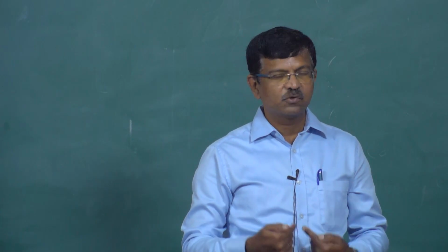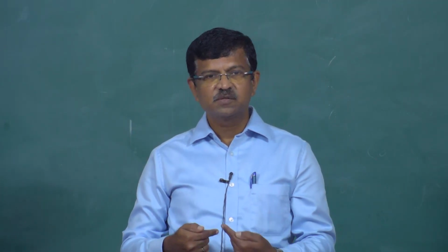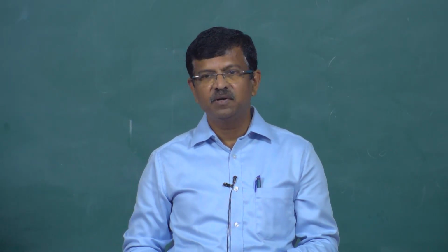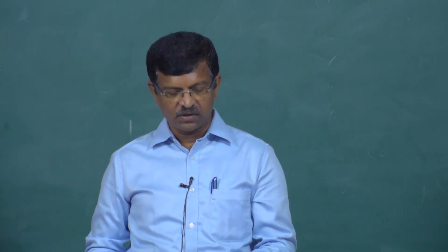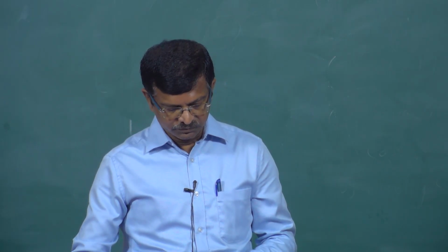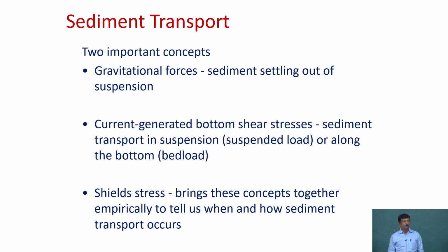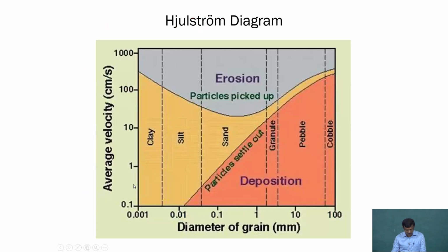However, the question is what is the bond between one particle and another particle; everything has been approximated in many theoretical senses. That is one of the important challenges that we always face. So, the Shield's parameter, very popularly known, is defined to make the balance of both, whether the sediment is going to be lifted up or not. It is a threshold value. More on the equation part etc., we will see later.